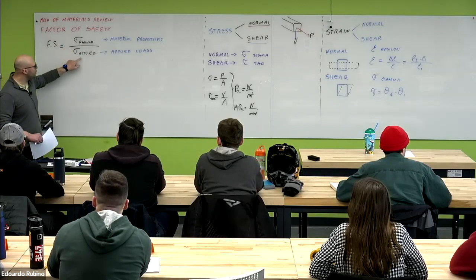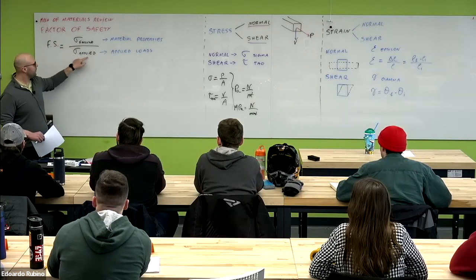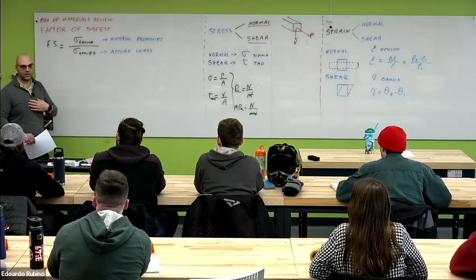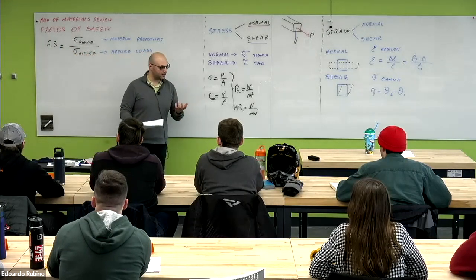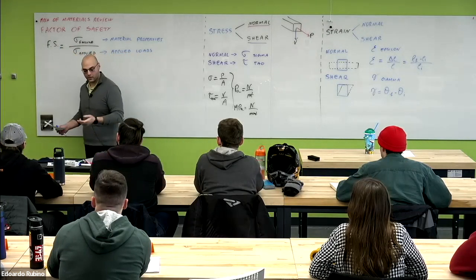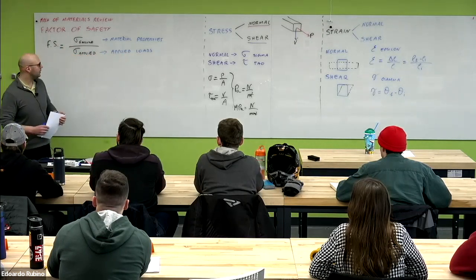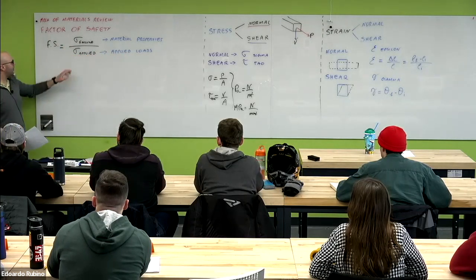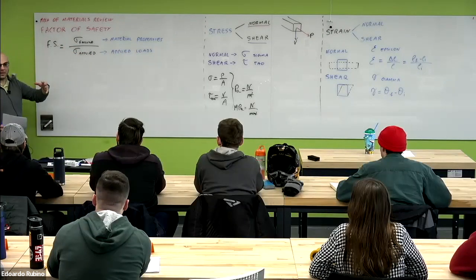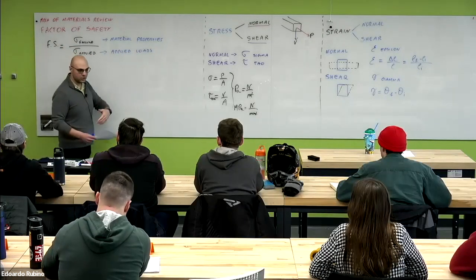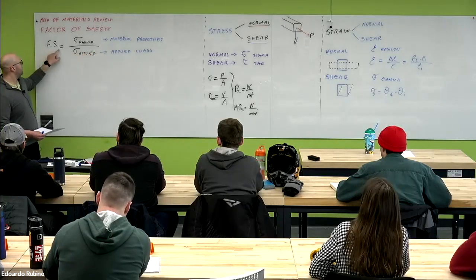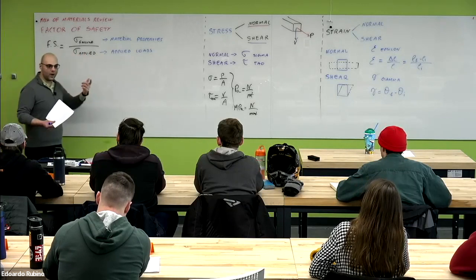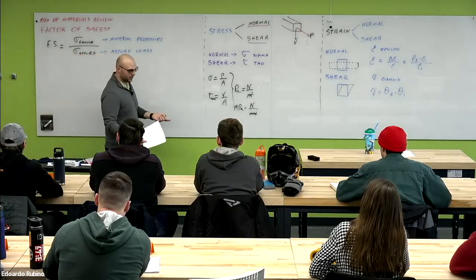If we want to reduce the applied stress, we can do that by changing the geometric characteristics of our structure. So we can think, okay, how about we always have a very small sigma applied? We make our structures very, very big, so we have small applied stress and always a very big factor of safety. Why can't we do this all the time?